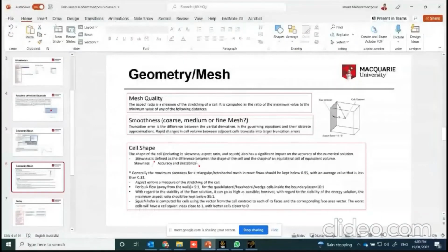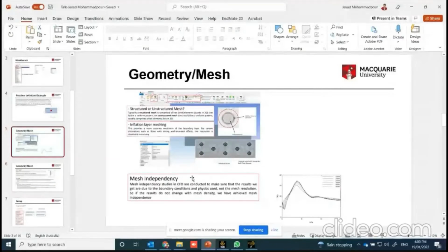I quickly review the mesh independence study. After that, you make sure your generated mesh is okay. You import it in Fluent, and you have to consider important parameters in your simulation and monitor them. You also have to check other mesh configurations, for example further refinement, because your solution should be independent of the size and the number of the cells.